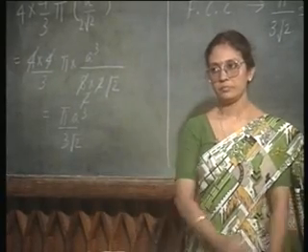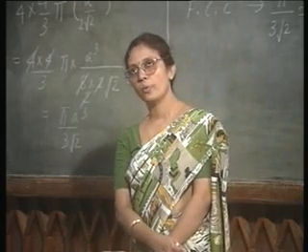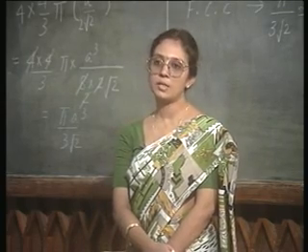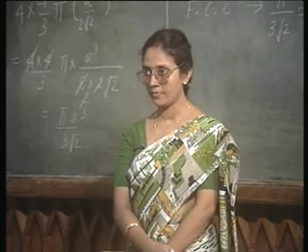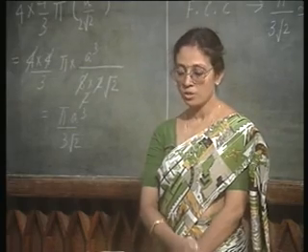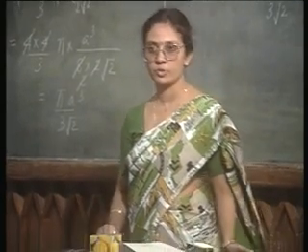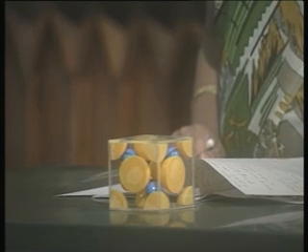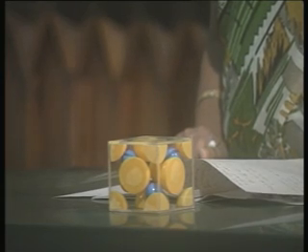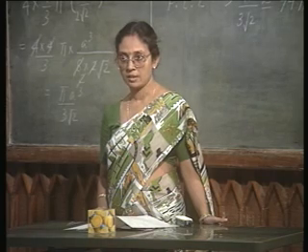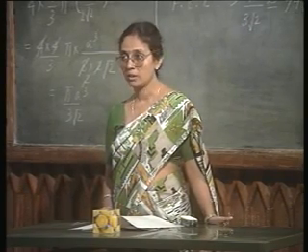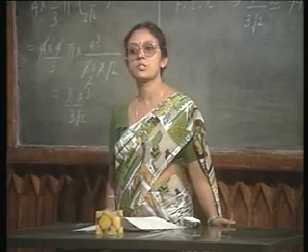Now, when we try to dope silicon, that is, we would like to introduce impurity atoms inside the silicon crystal, these impurity atoms should replace the silicon atoms, right. So, one or many of these positions should be taken by the impurity atoms. It should push the silicon atoms out and take that position instead, right. Incidentally, this is called a substitutional kind of introduction, that one impurity atom goes and substitutes one silicon